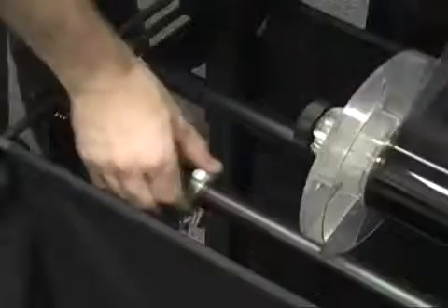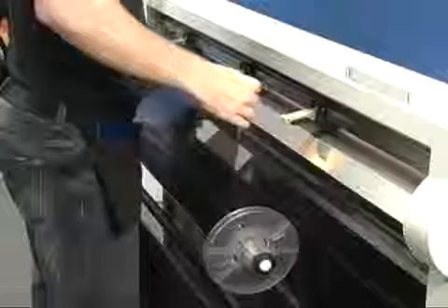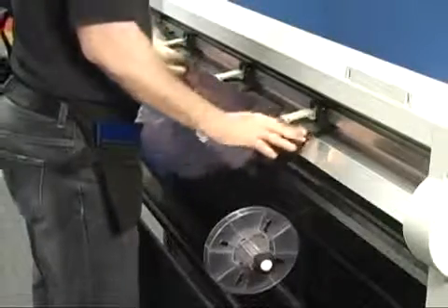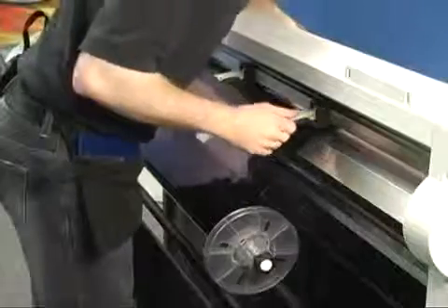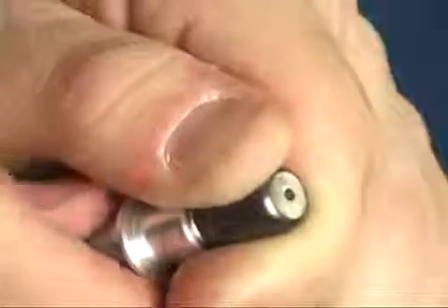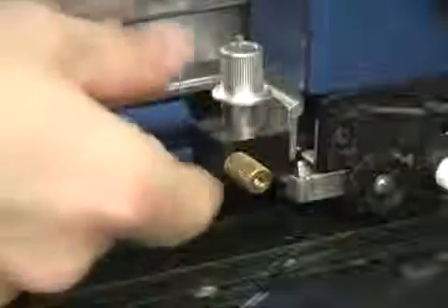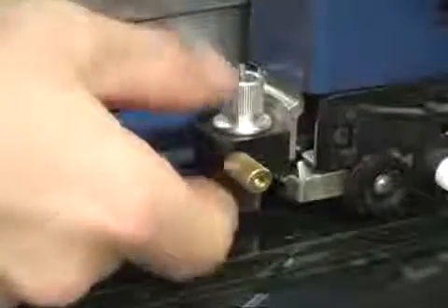The first thing you need to do is load the window film into the cutter. Next, you'll set up your GX400. Lock down the pinch roll wheels. Then set the 25-degree blade in the blade holder. Set the blade extension to the thickness of the film.